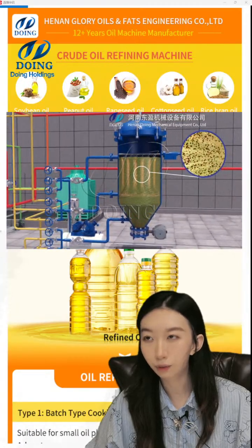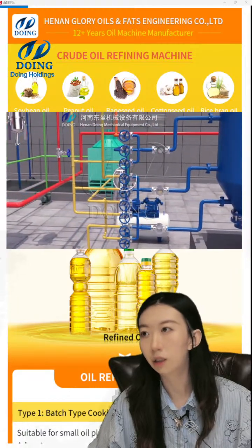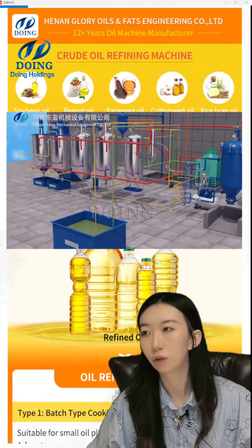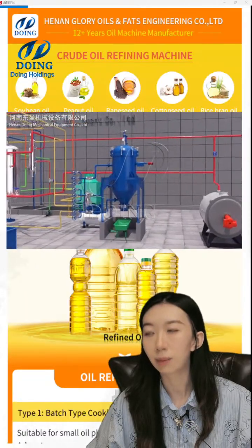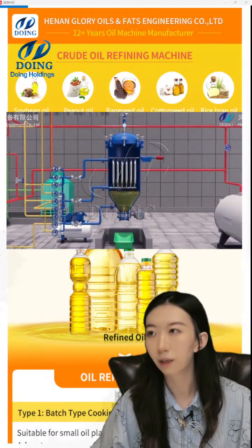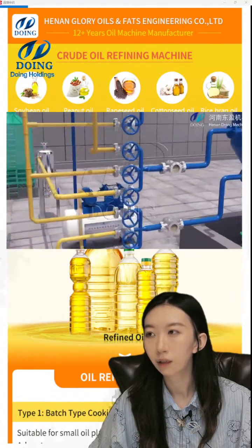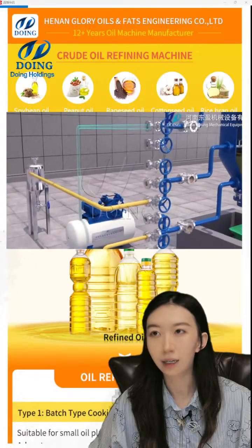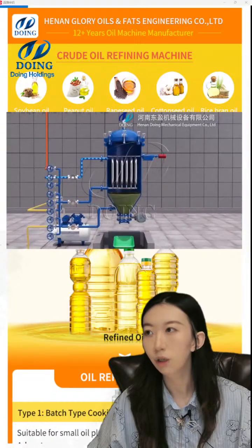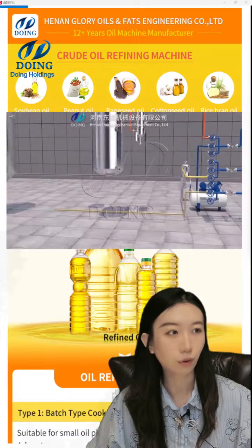And after filtering, the standard decolorized oil can be pumped to the decolorization temporary storage tank for the next stage. And the bottom oil has some impurities, so it will be pumped back to the decolorization tank to be decolorized again.